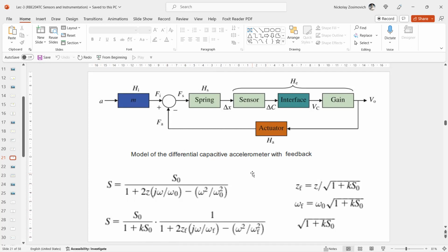For instance, pressure. Many pressure sensors are based on a flexible membrane that deforms when a pressure difference is applied. Usually, this deformation is measured by some displacement sensor providing the output signal. The effect of the strong nonlinear response of the membrane can be eliminated by feedback, as you can see here, using only a linear actuator in the feedback part. By the way, there are various sensors on the market that are based on the feedback principle.